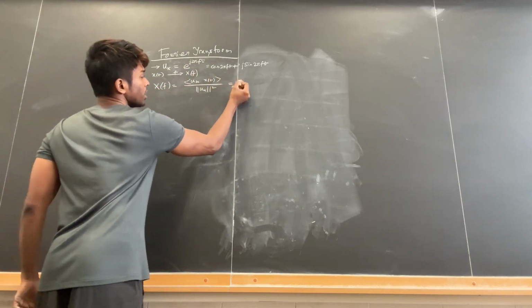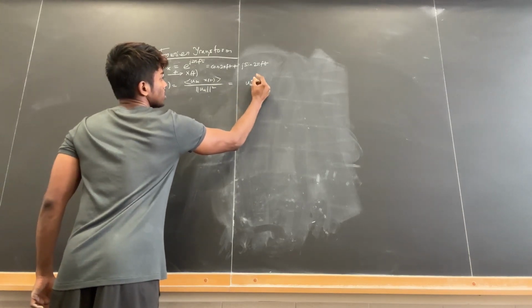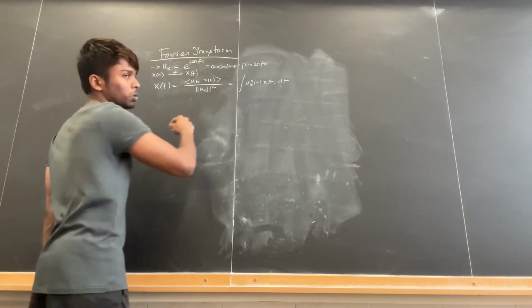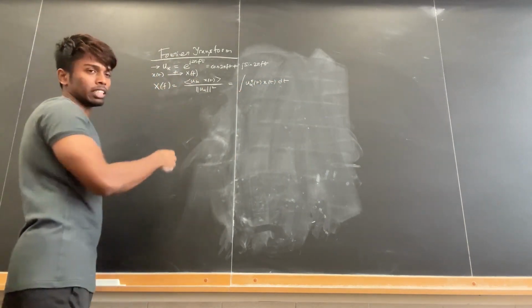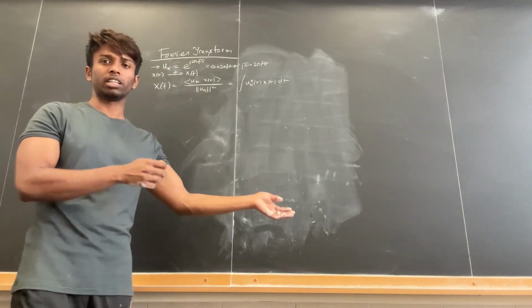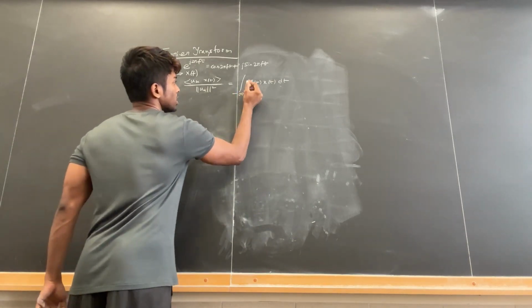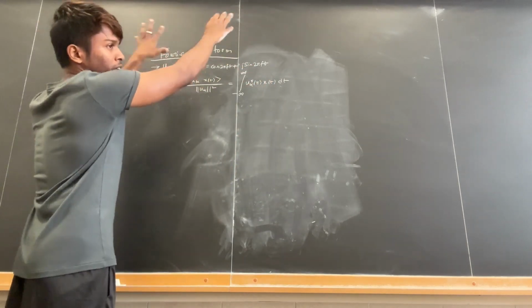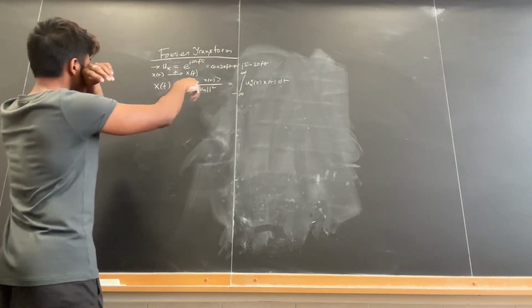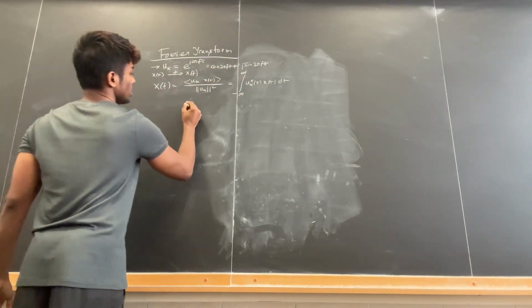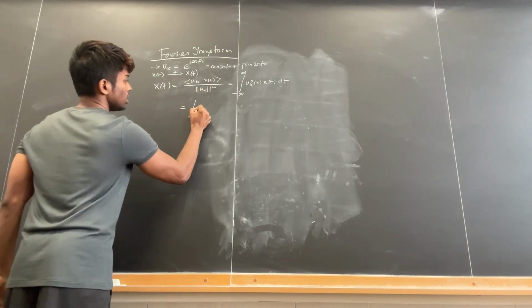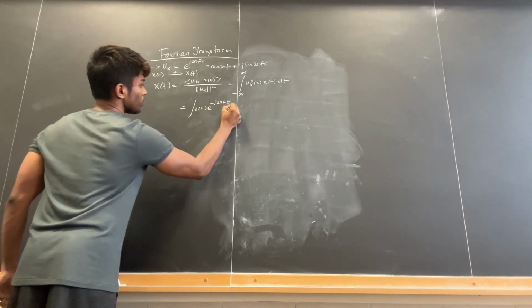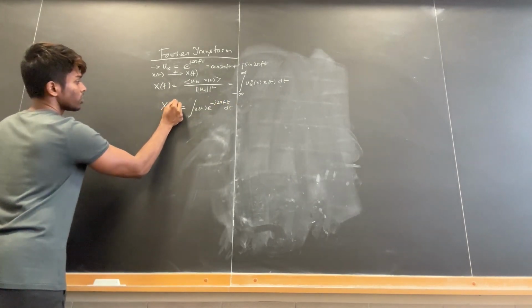The inner product is defined as uk conjugate t xt dt and integration over the total signal definition interval. We suppose the signal is a continuous time signal, so it is defined from minus infinity to plus infinity. So uk conjugate t. So this is a complex function. So a conjugate of the complex function is just a minus j. So ultimately we have xt times e to the power minus j 2 pi ft dt, and that is the definition of the Fourier transform of x.